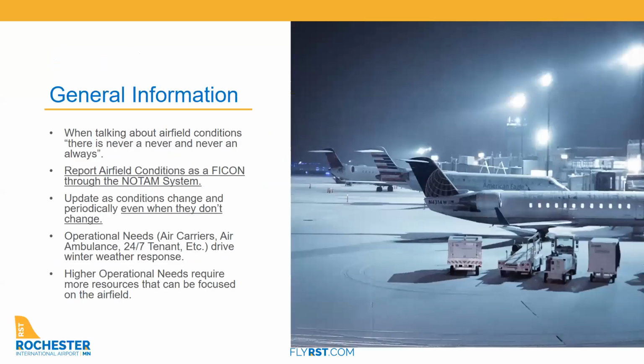Next, please. So, when talking about airfield conditions, one of the things I've learned over the many years I've been doing this is that it's really hard to describe any two snow events as being the same. So I would always say, there's never a never and there's never an always. As you try to describe to someone how to manage snow and snow removal, it's challenging because there's always different variables, whether it's surface temperature, type of precip, wind, air temp, lots of different variables.